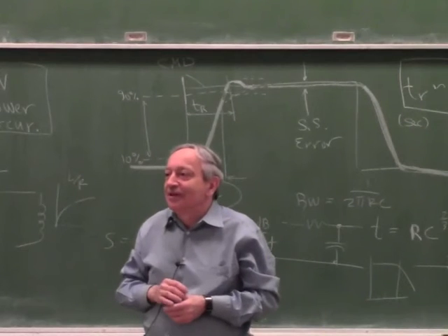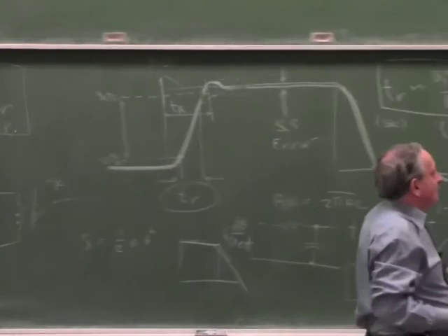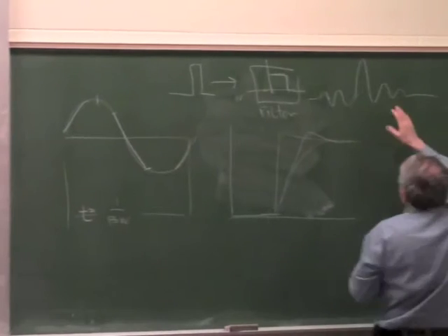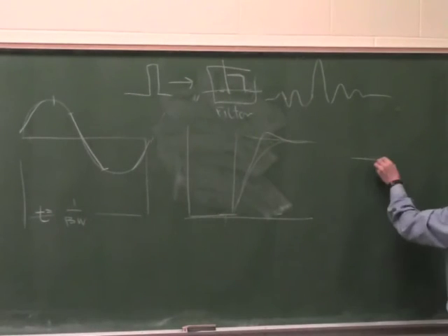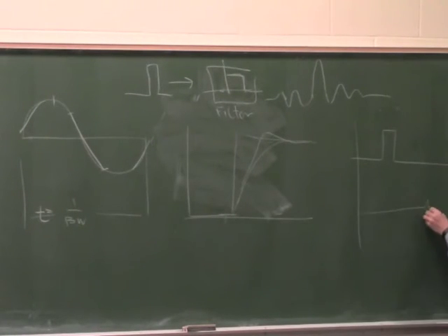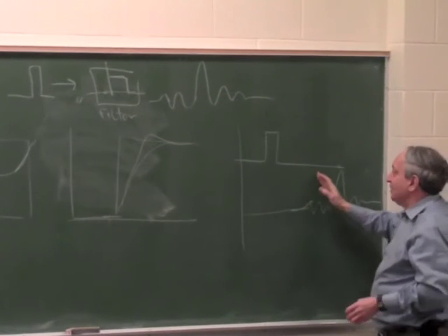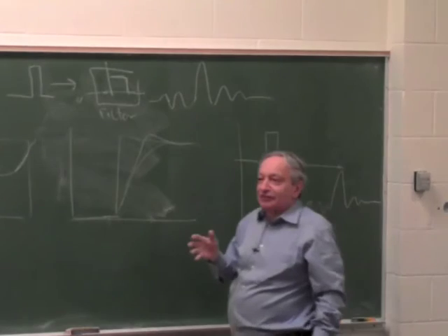Yes? The whole thing's delayed? Pardon? The whole thing's delayed? If correct, very good. Because actually, if you line them up in time, the input pulse looks like this, and the output pulse starts much later, because the filter has a delay. So, of course, it doesn't see the future. It starts ringing much after this pulse. And the more stages you have in the filter, the more delay you have. But the more delay you have, the worse it is for a servo system.